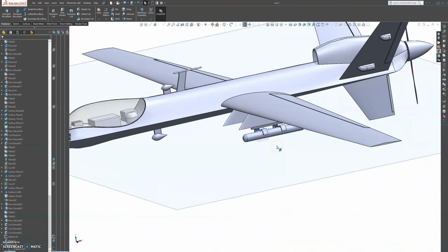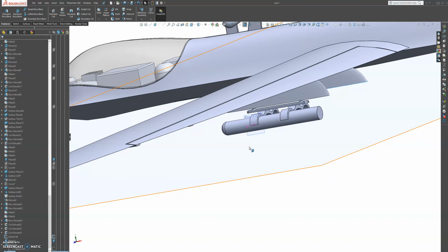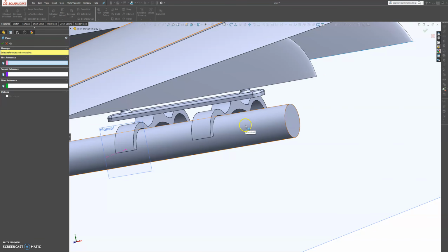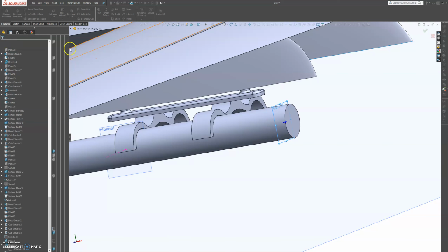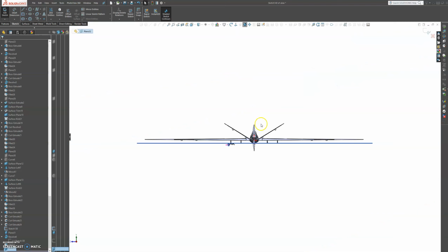And then let's add the tail wings to the back of this missile, and for that we're just going to create a plane, so we're not moving in from the actual edge. So let's create a plane, let's reverse that plane and make it into 2. That's perfect. Okay, and then we're just going to sketch on this plane. Normal to profile.